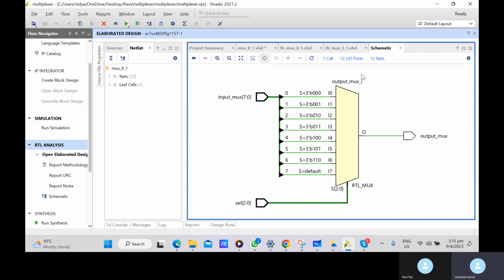It's pure mathematics. You remember when we multiply one digit, we shift and add a zero at the end. Multiply, shift, and add. Try it, and once you have that, we can easily implement the hardware for the multiplier.